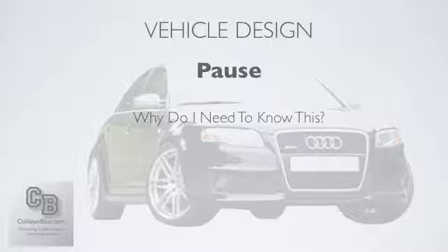If you don't really understand the concept, it's going to be hard to get it all in your mind of what happened in an accident and try to reverse that damage, because you've got to reverse whatever happened in the accident, first in, last out. And we mentioned crush zones. You need to understand those and know where they're located, because if you're going to section something, you never want to section in a crush zone, and that's something you need to know. And we'll talk about that in a minute. Some of the newer cars even have crush zones that you can't see, so it becomes that much more important to understand how vehicles are being made.